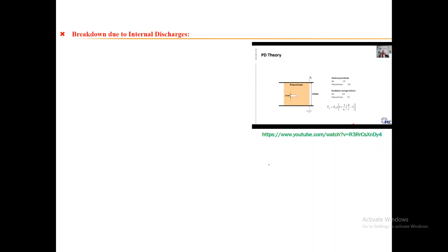However, the problem is that in our defect here, you've got some XLPE, then a gas-filled void or an air gap, and then more XLPE. What that means is instead of a uniform dissipation of the energy from the conductor, you get a localized area of capacitance, a localized area of stress. So as the energy in the power cycle increases, the stress very specifically at that defect point increases also. And as that stress increases within normal working voltages, you will get a very small low energy breakdown across that defect. It must be noted that breakdown is at the defect.